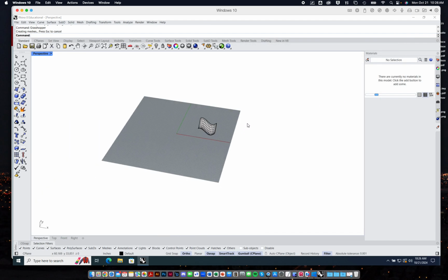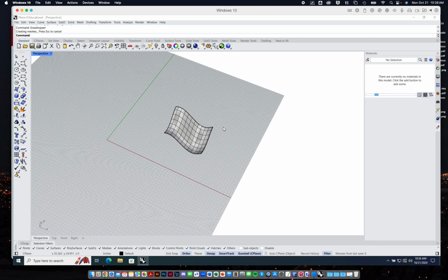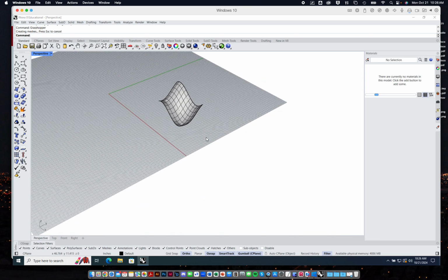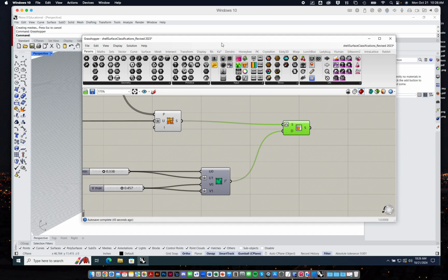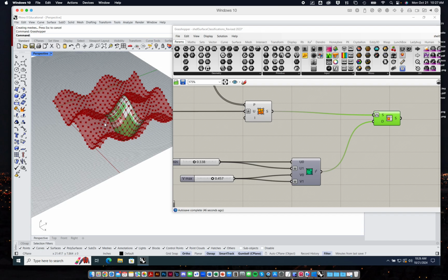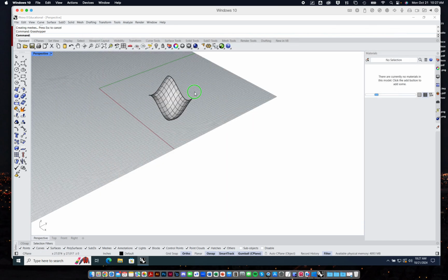Now I can close Grasshopper, and when everybody does this, you will have a master surface geometry for your grid shell. That's it. You're not going to have to make some curves of your own, lock them together, or anything like that. But this will ensure that we have a doubly curved surface. Again, I just decided where I wanted it with these sliders. And you can see that when I take this last widget and select it, it highlights that subsurface green. I can right click, bake it into Rhino. Now I have a static version of that surface patch.